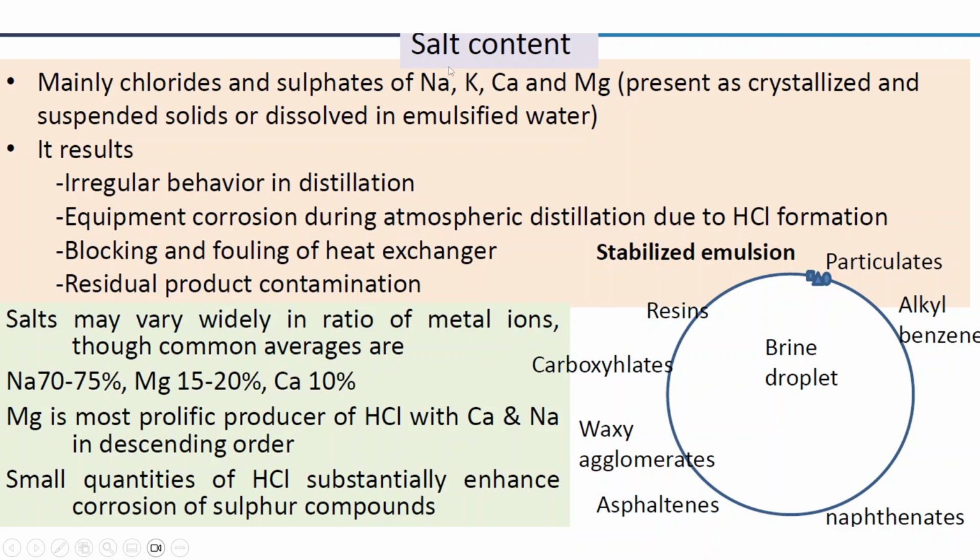Coming on to the salt content, our crude oil consists of various salts also, mainly chlorides and sulfates of sodium, potassium, calcium, and magnesium. They can be present in the crystalline state, or may be suspended solids, or dissolved in the water present in the crude oil. The various problems that occur due to the presence of these salts are irregular behavior in distillation, equipment corrosion during atmospheric distillation due to HCl formation, blocking and fouling of heat exchangers, and residual product contamination.